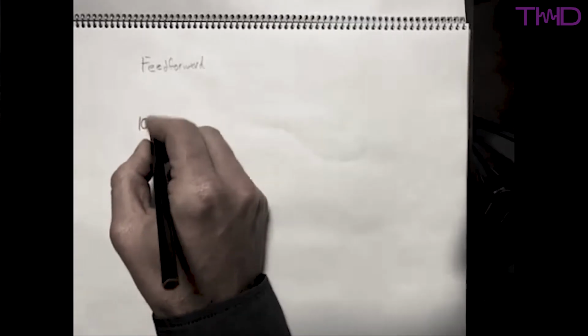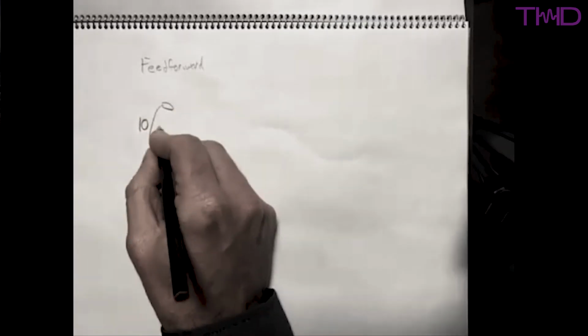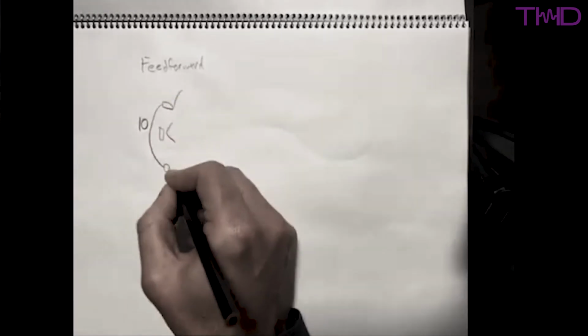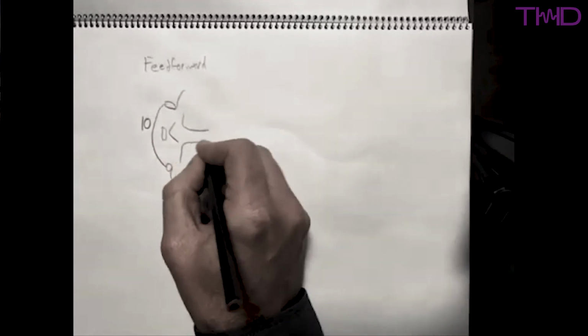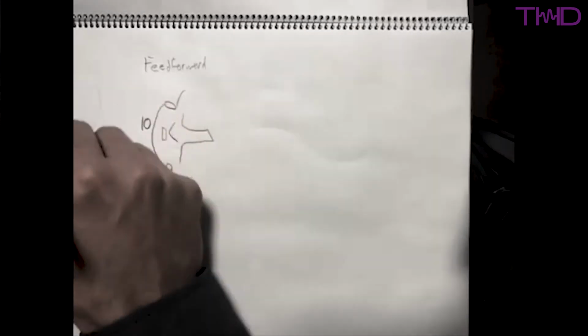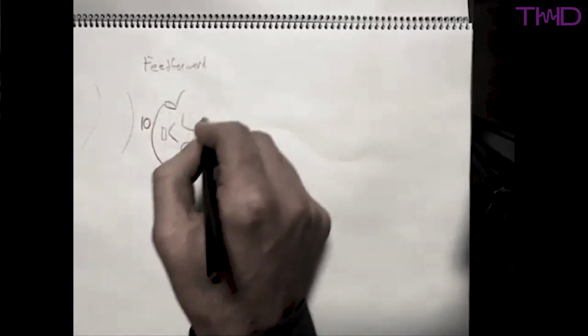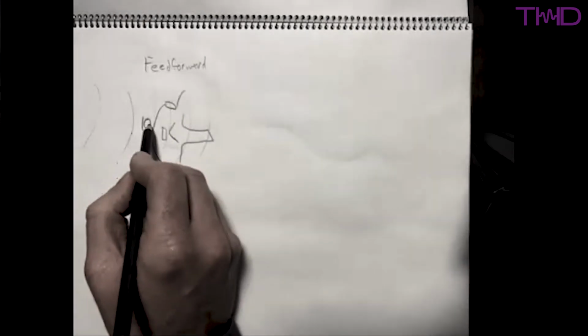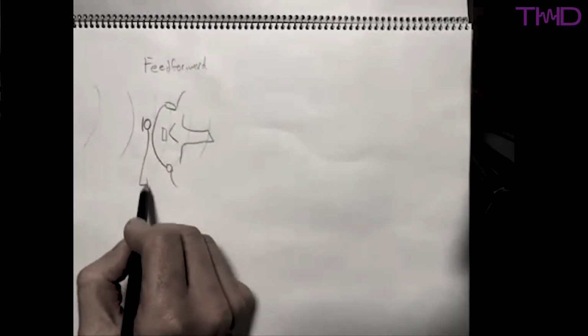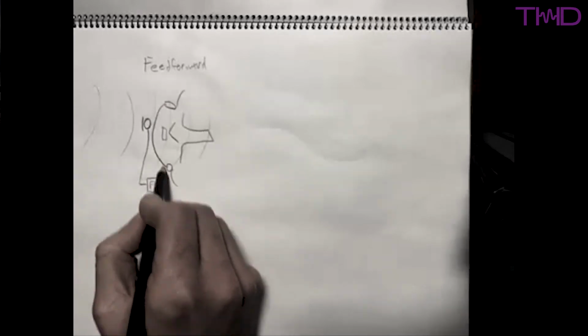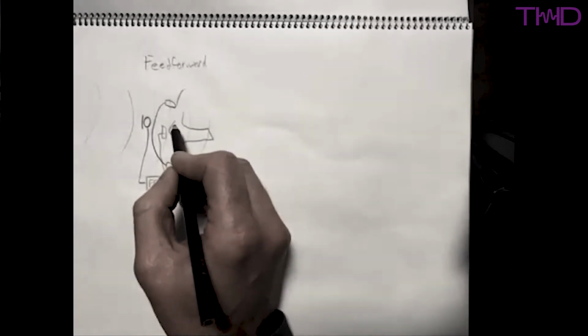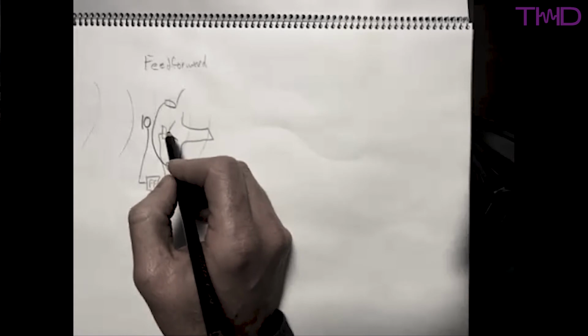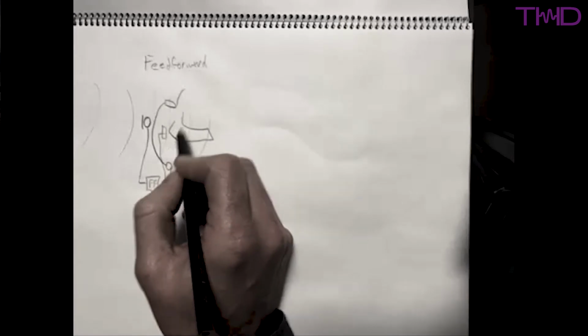So in feed forward, the microphone is outside the ear cup. I'll draw my microphone as a line in a circle, and then the ear cup here, the speaker, there's your head, there's your ear canal. Again, sound comes from the outside, passes through everything, and reaches your ear canal. This microphone picks up a signal, passes it through some feed forward filter, and puts it out of the speaker. The simple case, more easy to comprehend, is where you just want that to be the opposite waveform.